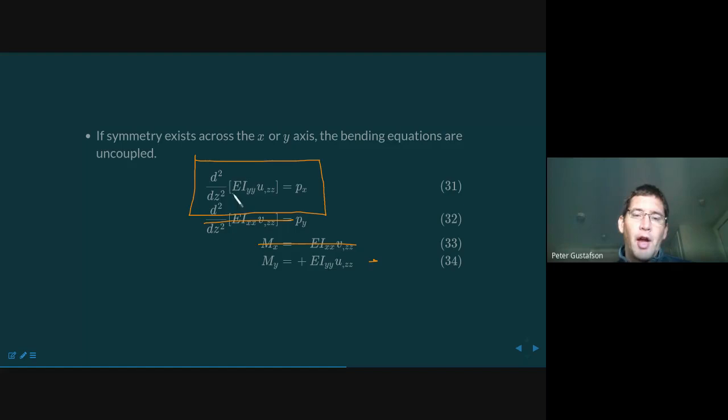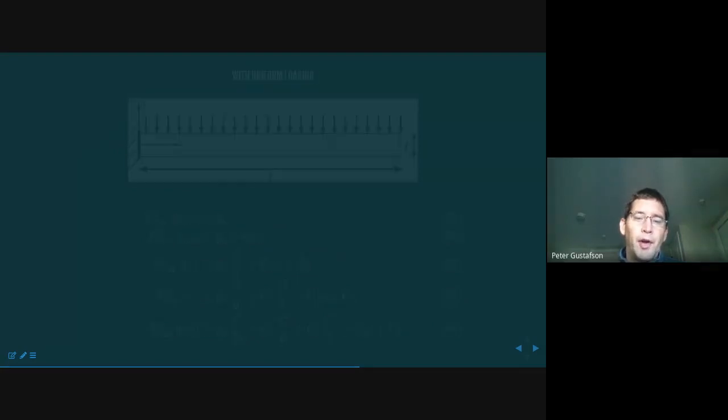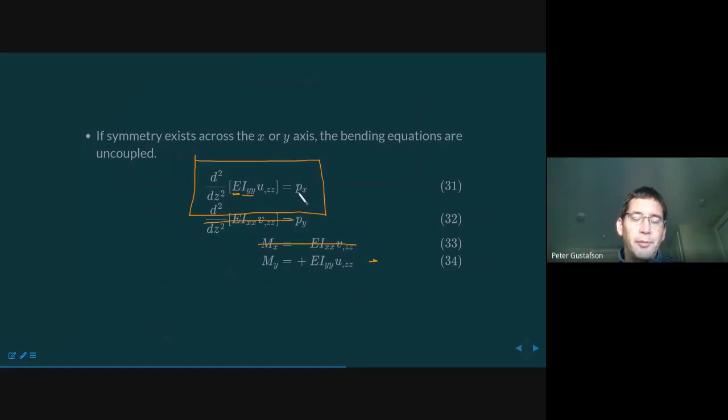That is, it's reasonable to assume that the Young's modulus is constant over the beam. And unless you're told otherwise, or if the image indicates otherwise, it's reasonable to assume that the area moment of inertia is also constant over the entirety of the beam. If we look at this image on the screen, there's nothing here to suggest that that assumption is not true, and so it's reasonable for you to state that as an assumption.